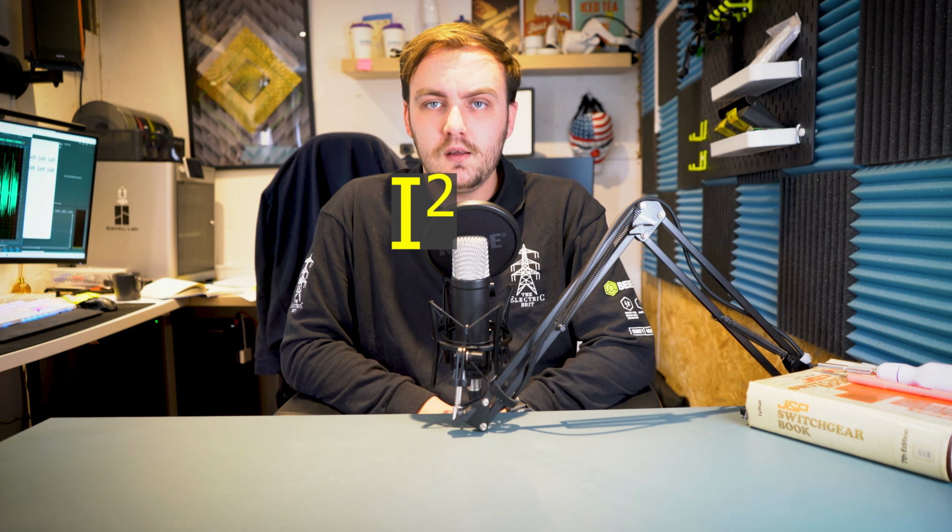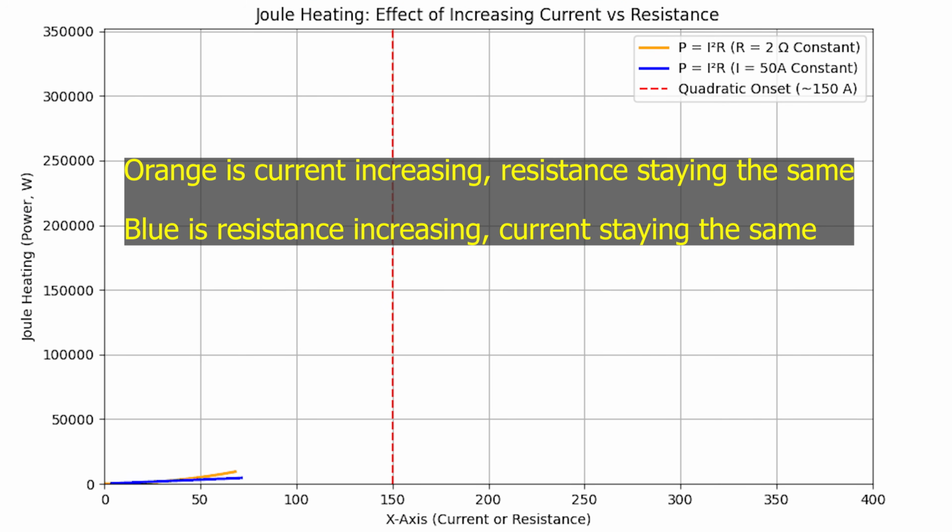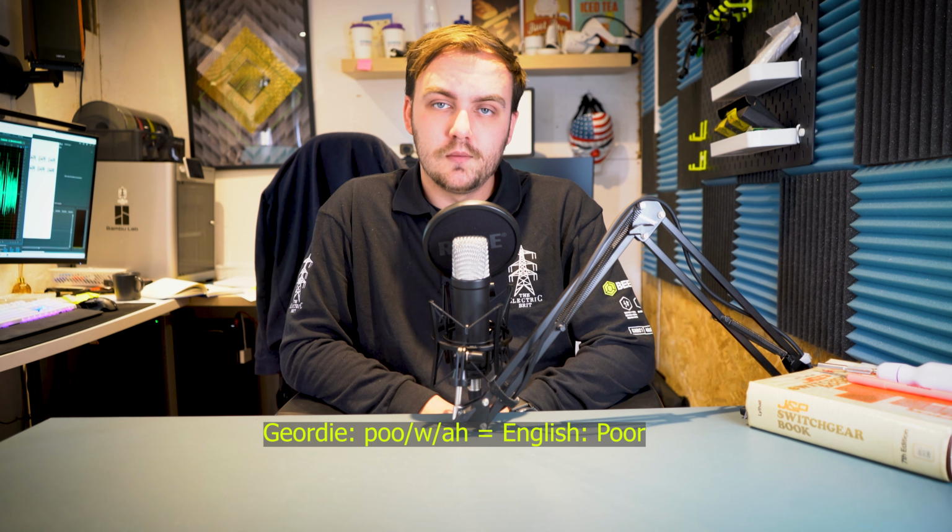A key factor on why more current means thicker conductors is Joule's heating, or I²R losses, which state that the power lost due to the resistance in the transmission lines is proportional to the square of the current I multiplied by the resistance R of the conductors. Therefore, P equals I²R. This means that even a small increase in current can lead to a significant increase in power loss. It's also why high resistance joints and poor connections heat up.